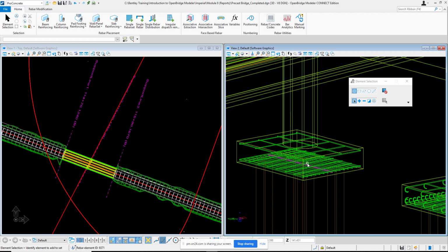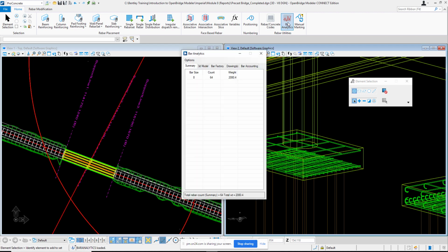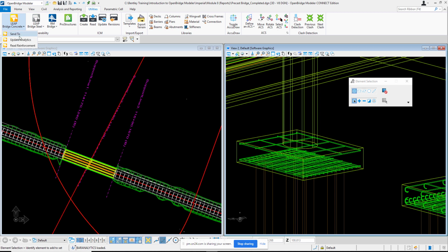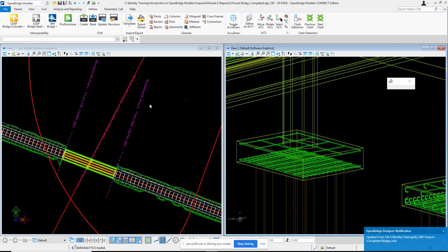And that is the advantage as well of generating this BIM workflow, because everything connects to each other, right? And with this option, you can get quantities and all of that, right? You can get the bar analytics happening on this project too, right? So you can see this is a direct connection with analytics. Now, when you run your calculations, you maybe set up load combinations or something different in Leap. You're not going to lose that every time you update analytics. So you may change a footing size, for example, and then just say, update my analytics, right? It will go update the analytical model, and when you send it to Leap, it will just retain those calculations, and it will just update the new dimensions. Okay?